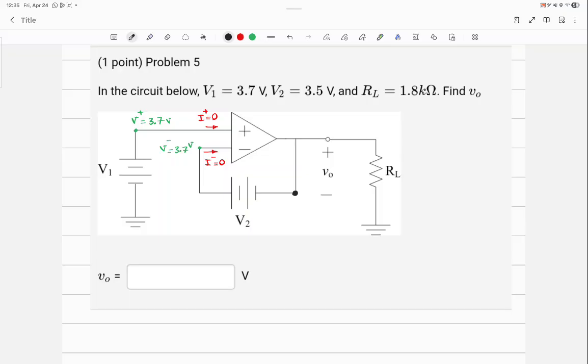What's the voltage of the black point? Wouldn't it just be V2 because it's the difference between V2 and ground? Where is ground? At the end of that was a resistor. Here? But nothing to do with the black point. They are not connected anyway.